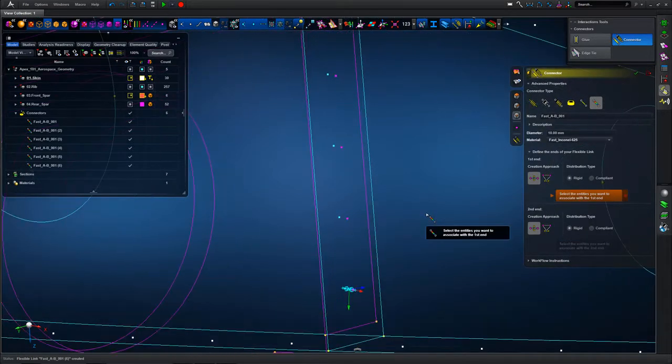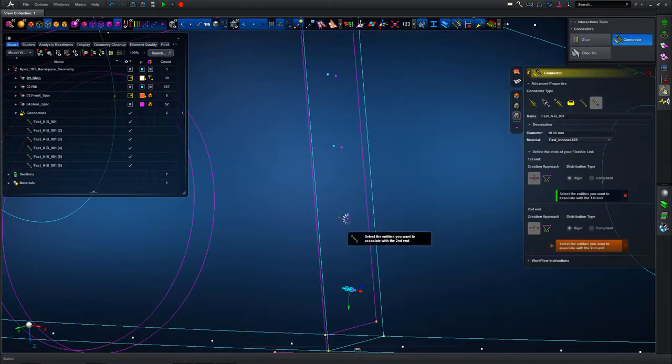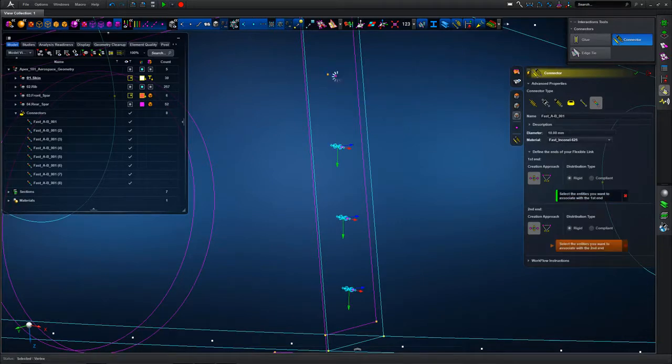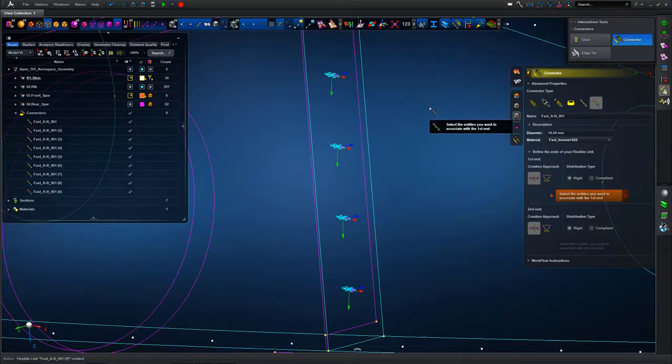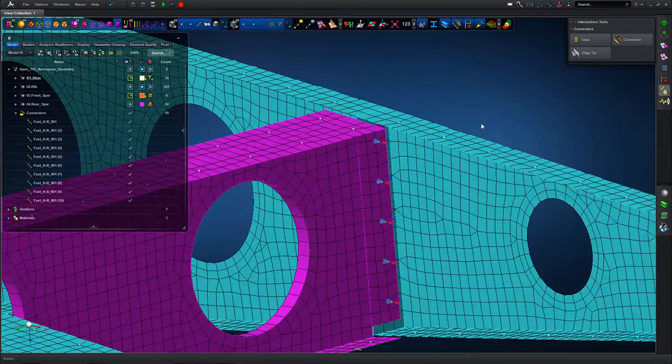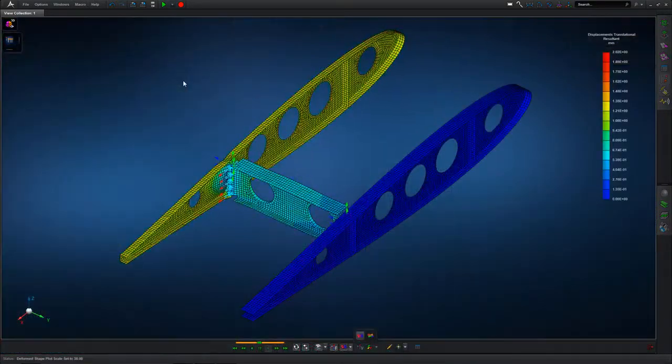Again, so auto execute turned on so that we can quickly cycle through the model definition and create the fasteners as required. And you can see in the tree, as we create those fasteners, the fastener list is populated, again for viewing control and or editing, based on the standard Apex definition.